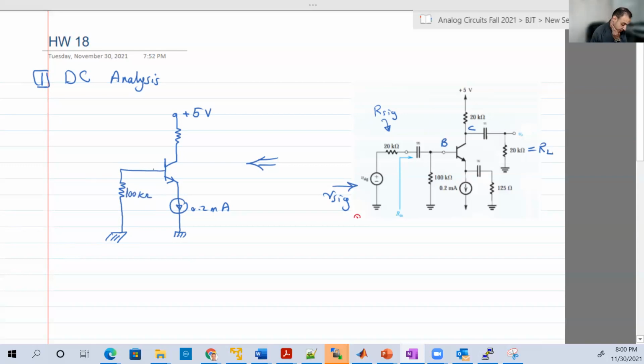Okay, good. So let's now try to calculate. We do the DC for 2 reasons: to calculate r pi or gm, whichever you like, both are equivalent and functions of one another, and to be sure that we are really working in the active region, because this is an amplification application, so we must be working in the active region. This is for sure an amplification circuit. The purpose of this circuit is to make the AC analysis, so don't worry about the verification.